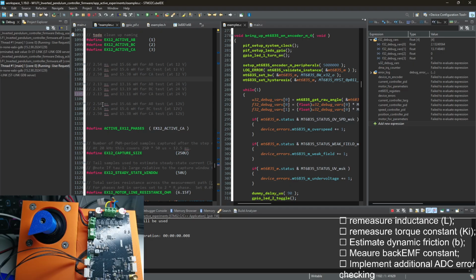And I hit, so let's calculate. At 24 volts, we should hit roughly 4 amps, because we have around 6 ohms. So with my power supply, it can only provide 5 amps. We cannot get much higher. Maybe we can go to 30 volts, but this will be the limit. 30 volts is not that much to compare against, so we might as well not do it.